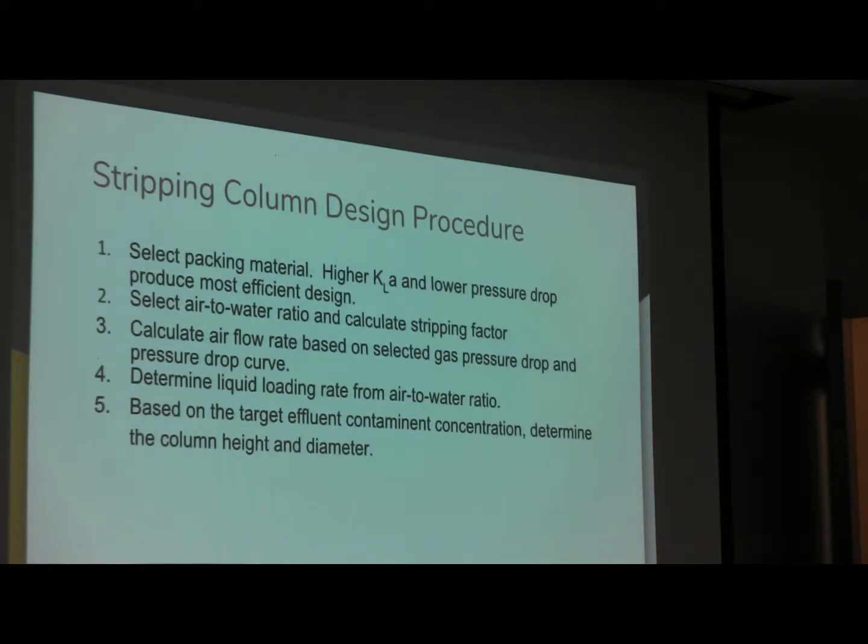There are several designing procedures. First, we want to select a packing material which has a higher KLa and lower pressure drop, and then select an air to water ratio that will help us determine the stripping factor R, and then calculate the air flow rate based on the gas pressure drop curve.